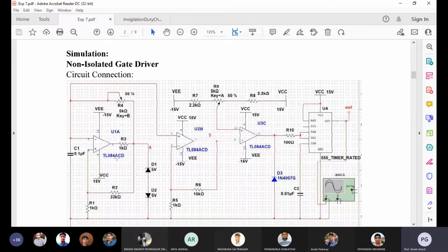Whatever sensing is there, we complete the sensing through transducers. Any physical signal can be converted to electrical energy. That's why transducers are very famous in this domain. Then we get the signal. That signal strength is not very high, so you have to amplify it and scale it to a comparable range of your reference value. Only after that can you compare. Otherwise you can compare, but the results and calculations will be wrong.